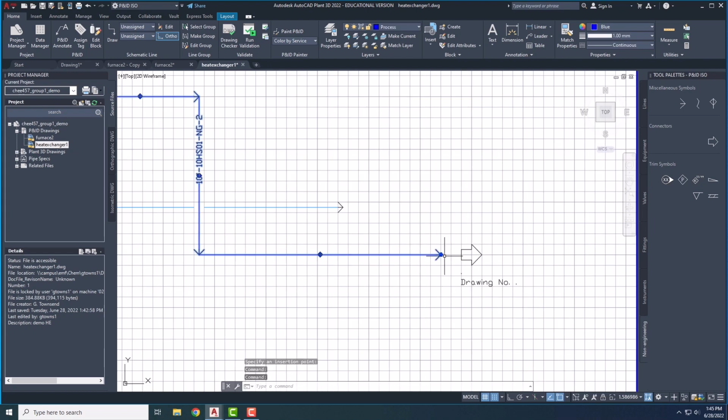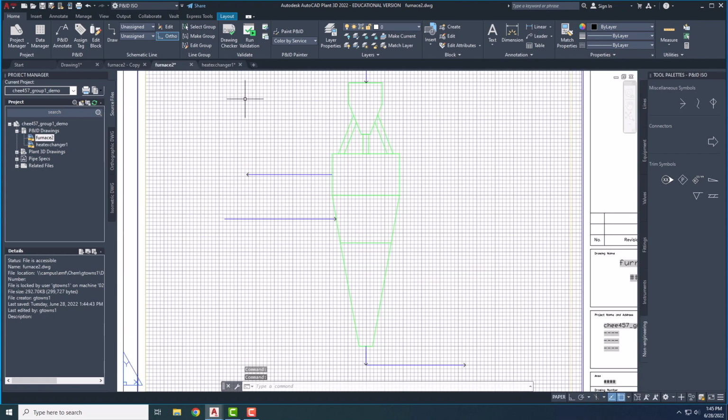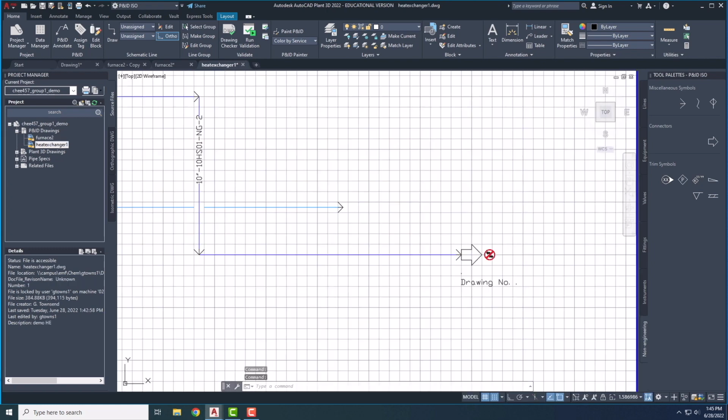Then this is the connection point of a pipeline. Click it, then just drag it as far as you need to go. Look for that node, click it, and now you can see it's connected to this off-page connector, and this off-page connector doesn't know where to go. That's what that symbol's for. So let's go put one with our furnace as well. Might have to save before so it recognizes it. We'll go to our furnace as well.